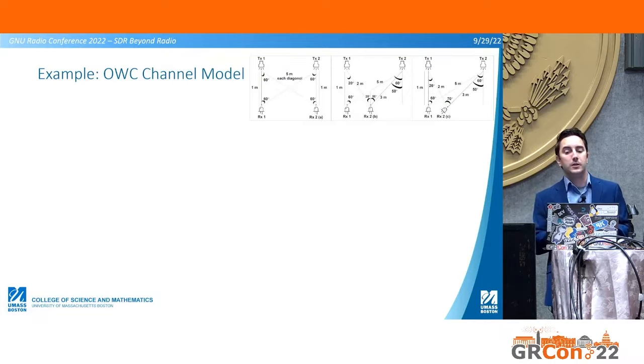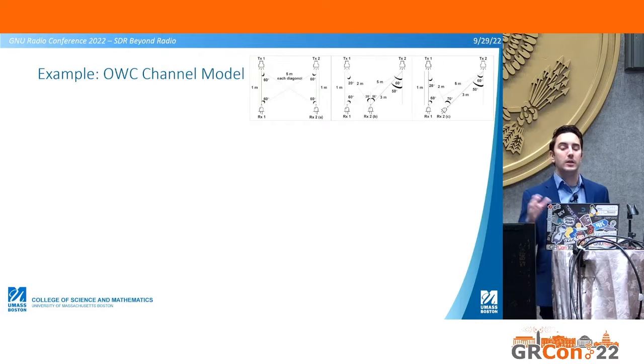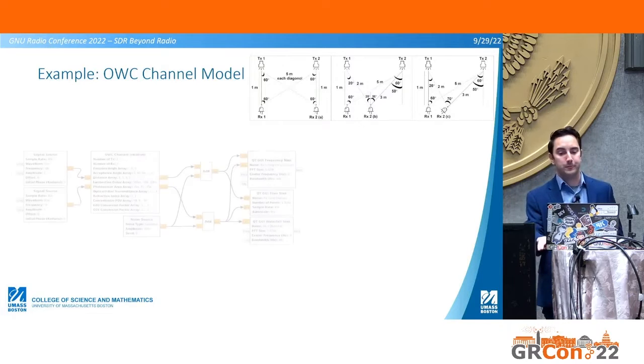If we bring that RX2 over closer to TX1, we're getting interference on both sides, picking up both of those signals. And then the impact of orientation, as we rotate that RX2, we get to see a stronger signal from the original transmitter, even though we're closer to that first transmitter.